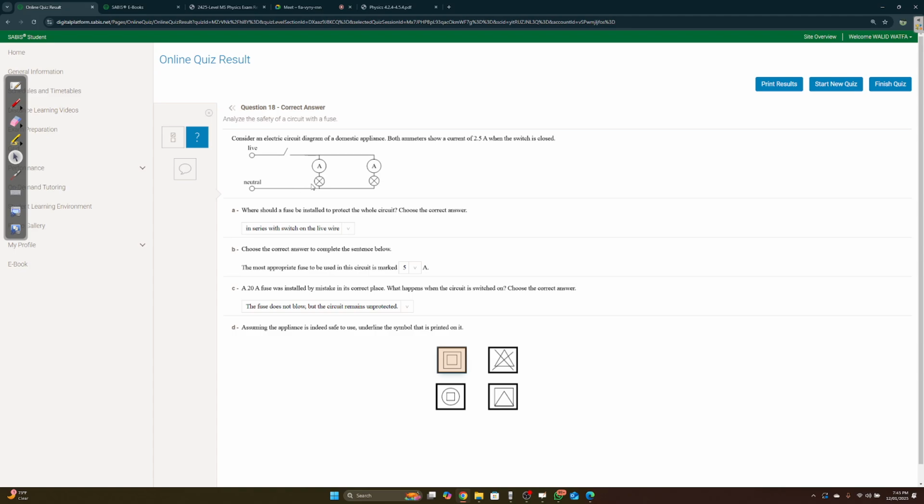But the problem is if you have overcurrent, to 8 or 9 amperes, it will be unprotected and the circuit will have melting, whatever. So it will remain unprotected because you use the 20 ampere fuse. Sure, what's the point? No way the circuit is going to overcurrent all the way to 20. You know what I mean?